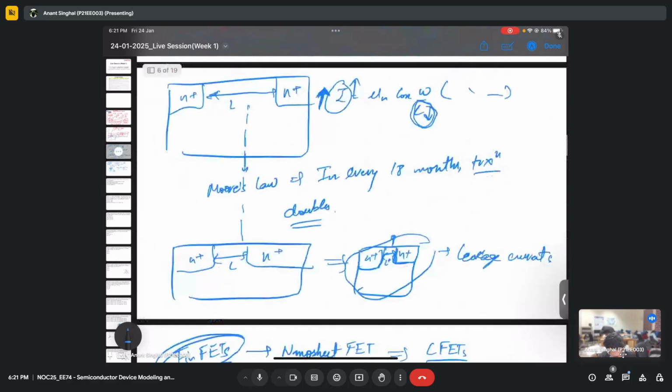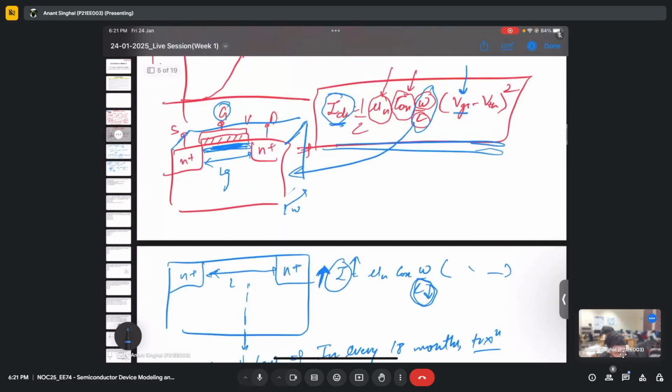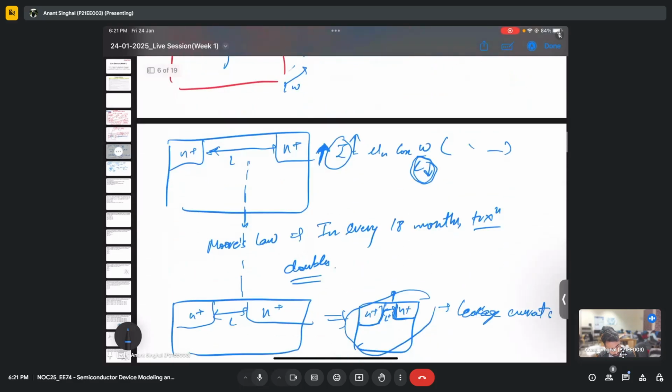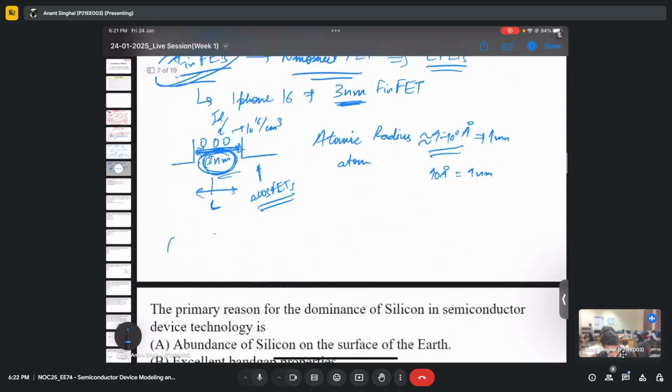As I said, MOSFET has certain equations. A compact model is again the file which has all the equations to capture the device behavior. If I talk about any industry standard compact model, there is a group called the BSIM group. There is an industry standard compact model which is known as CMG.